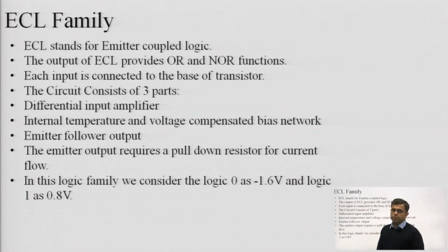So let's start with the ECL family. ECL stands for emitter coupled logic. The output of ECL provides OR and NOR functions, like the NAND gate was the basic function realized by the TTL. Similarly, ECL offers us OR and NOR gates, and NOR is a universal gate. We can realize all other gates using that NOR concept.